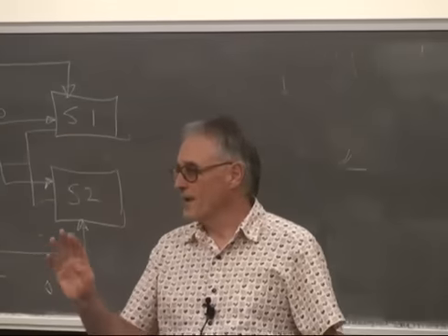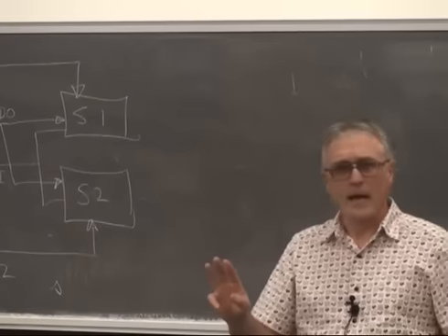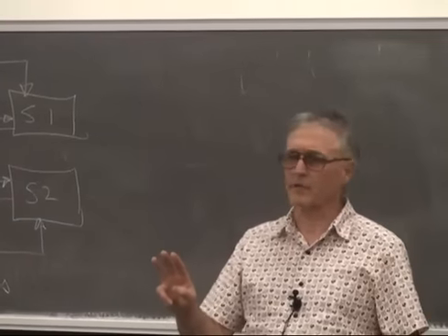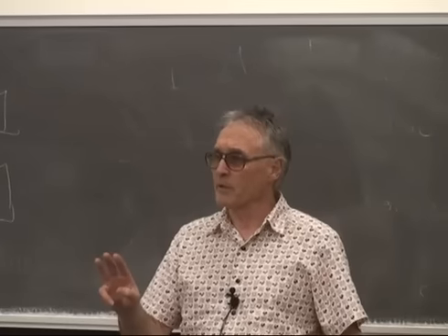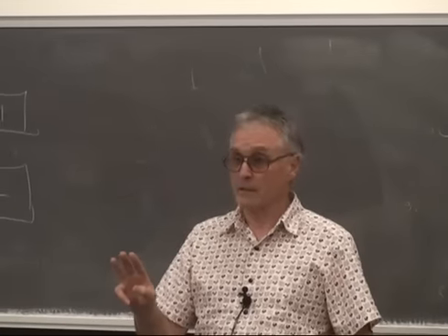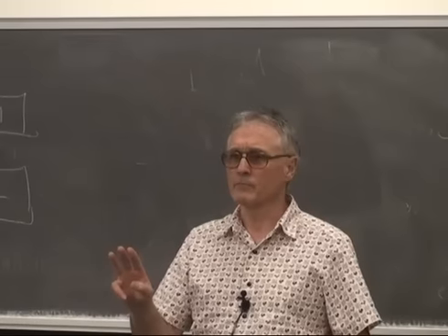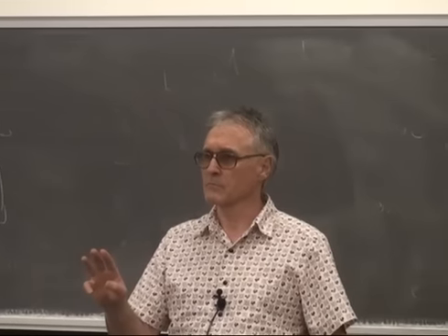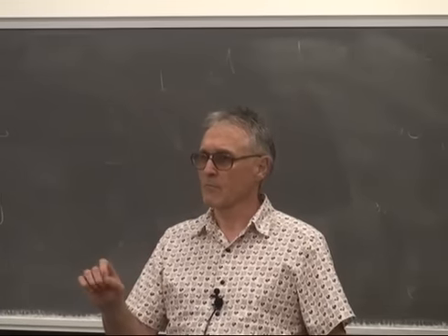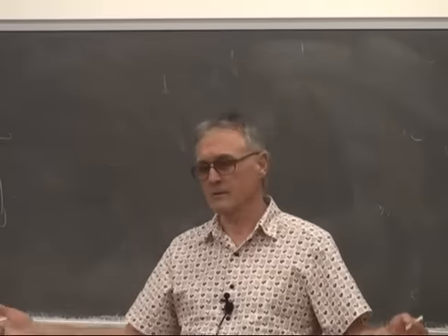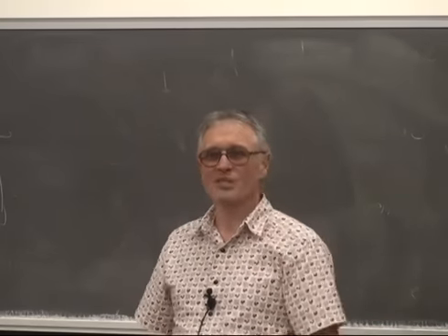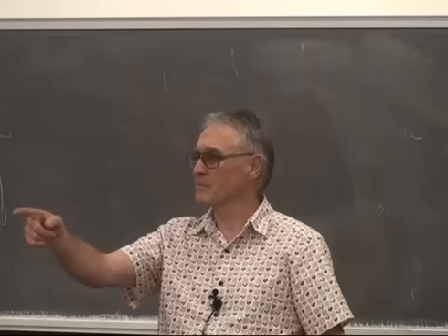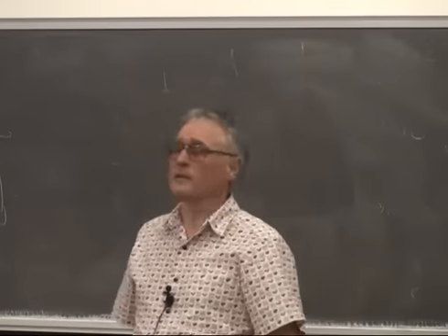The critical thing that you may not know yet is how long does it take to get in and out of an interrupt? If it takes longer to get in and out of an interrupt than it does to just wait, you shouldn't do it. Who wants to guess? Just wait. And you'd be right.